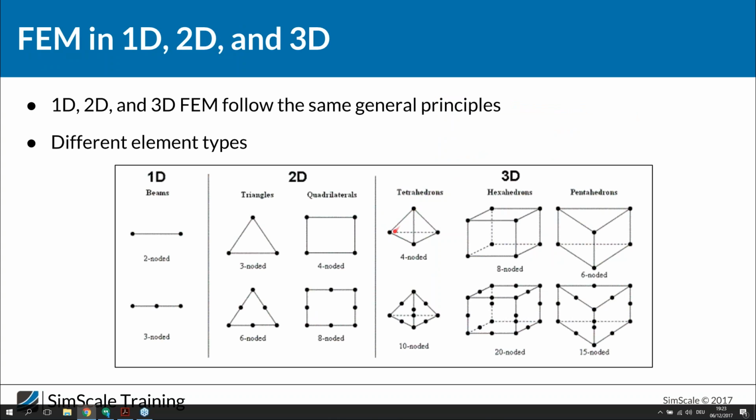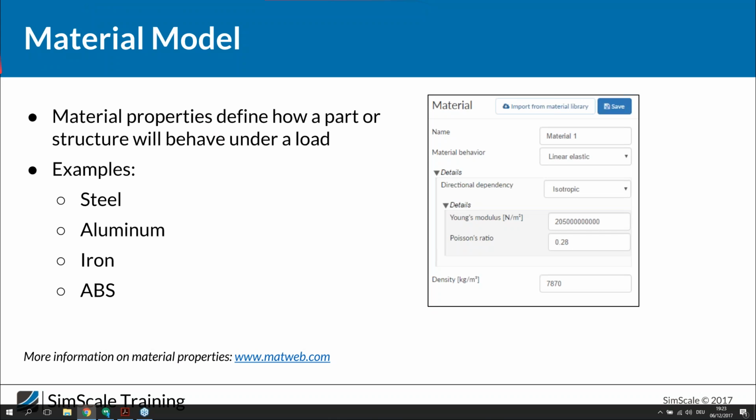So we need the stiffness to, you can also imagine, if you want a mechanical explanation, just imagine the edges of the elements as being the direction of springs fastening the model together. And when it comes to material modeling, you have a lot of different options. On SimScale, the great thing is we have a material library where you can easily import materials and easily describe materials on your own based on the standard mechanical properties. Here is an example for steel.